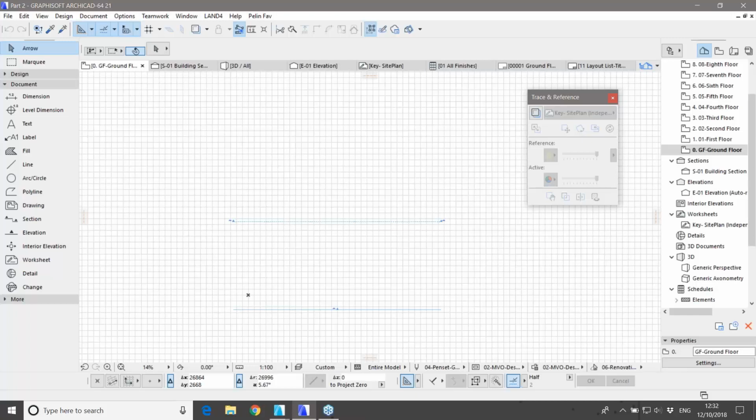So we'll start with a conceptual mesh modeling stage, and then we're going to make our way up all the way to the construction. So what's the first step you do when you start up a project? You receive a 2D DWG file as a site plan. Like I previously told you, we have worksheets in ArchiCAD. They're completely independent. Anything coming from outside sources in 2D, dump them onto the worksheets. That's exactly what I've done.